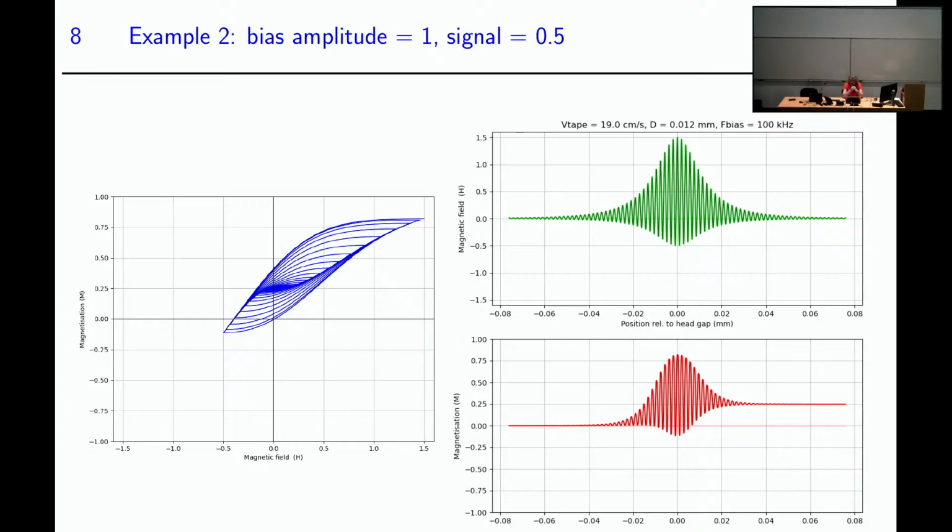And if you look at that with practical tapes, with the normal tape speeds and head dimensions and so on, that would mean several hundred evaluations of this nonlinear thing. Not only nonlinear, it also has hysteresis. Several hundred evaluations for each output sample. And an output sample at a sample rate of 1 mega, at least, to make it more or less correct. So you get a complexity of sample rate 1 mega times 300,000 quite complex operations per second for one channel. It's just too much.